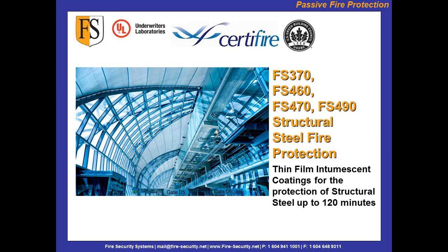And how do you measure the fire exposed perimeter? Well, that's the heated perimeter. It's an equation of heated perimeter over the cross section of the steel itself. So it's a calculated equation. You'll take the heated perimeter, every inch of perimeter of that steel section.